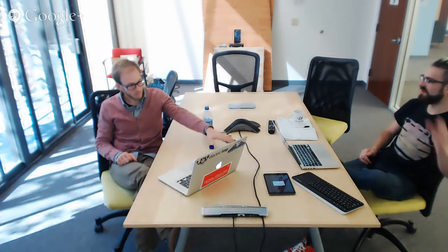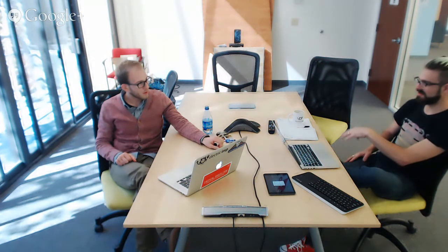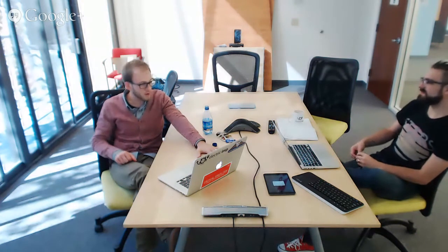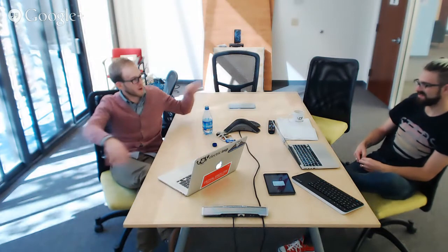Gotcha. So of those 2, you need one running on the BLE device or the peripheral, right, and then the BGLib port running on the imp device to talk to it. BG API image on the BLE112, BGLib class in your imp firmware, and then you can talk Bluetooth to Bluetooth peripheral devices. Cool.